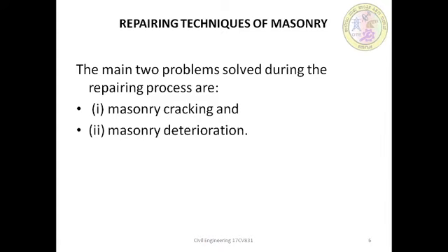As far as masonry cracking is concerned, in general a crack may be defined as a break, split, fracture, fissure, separation, cleavage, or elongated narrow opening visible to the normal human eye, extending from the surface into a masonry unit, the joint or interface between the masonry unit and adjacent mortar joint, or into a joint between the masonry and an adjacent construction element.